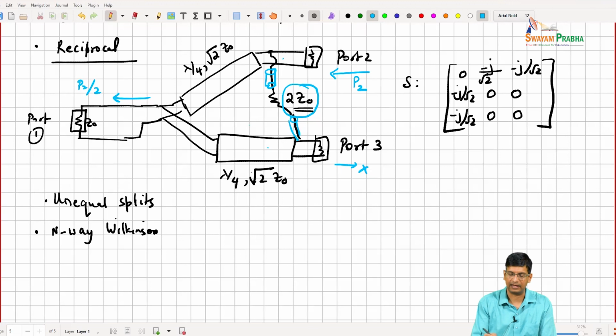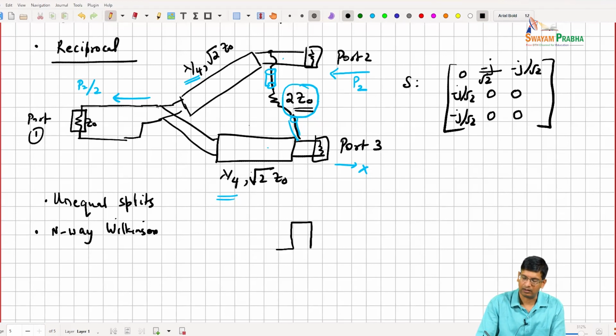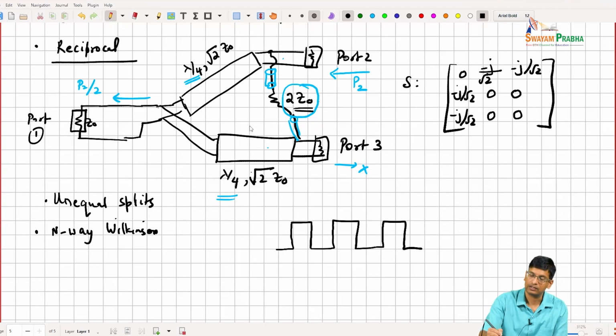And you can see that basically the size of this is going to be on the order of lambda over 4. But one way in which we typically can try to reduce size, if we just do want to use transmission line circuits, is that instead of using transmission lines that are just straight, we basically meander the transmission line. So this is basically, let's say, my CPWG structure.